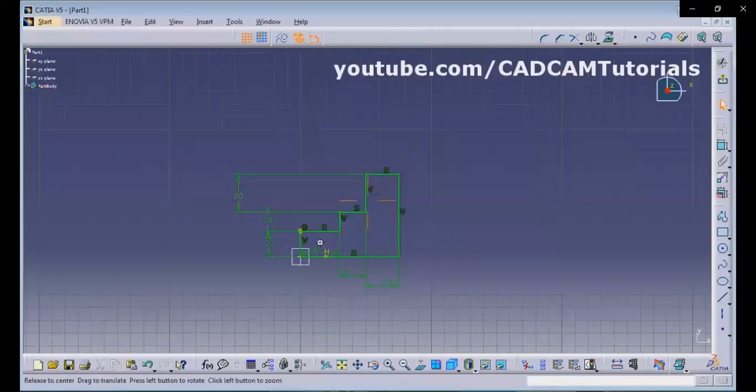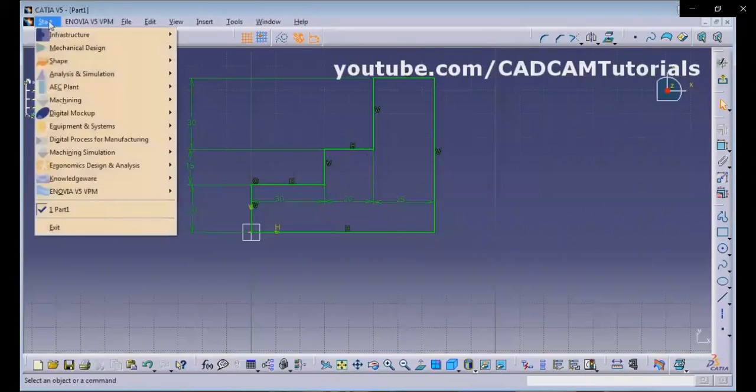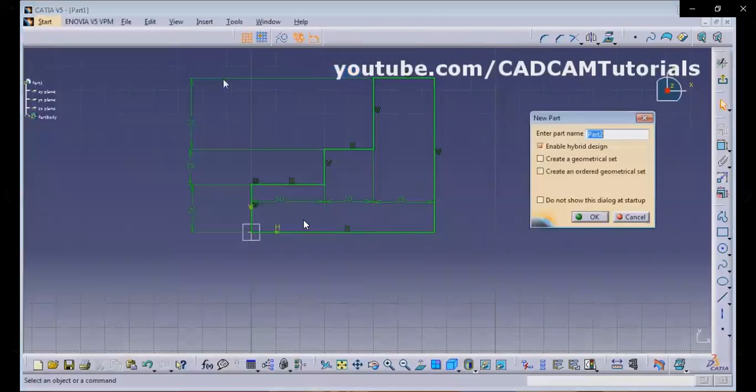So in this way this first object is ready, and it is fully constrained because all the dimensions have been given. To bring the dimension in line, click and hold on the arrow and drag it. Drag the arrow, and drag the text to place the text properly. So in this way this sketch is ready. As it is not very important, we will not be saving it. So again we will start a new sketch: mechanical design, sketcher.